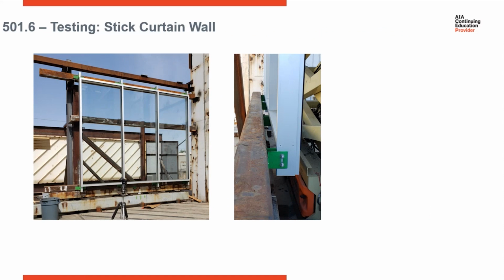Again, this is just another picture of the actual test chamber. So you can see, mimicking real-world solutions. Again, your simulated slab, which is these steel tubes, and you have your wind load anchor here, and then over here you have your dead load anchor. In this case, this top steel tube is fixed, and then your bottom tube can rack back and forth to simulate the seismic activity.